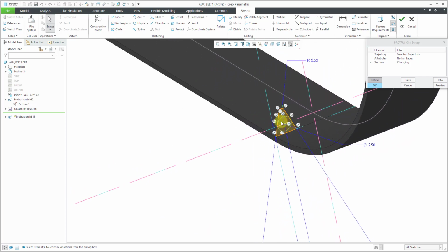I could have just taken the dimensions and figured out how to recreate it, but instead I hit the save button when I was in sketch mode in order to save this sketch out to disk, and then I found it where it was on my computer. I renamed it and dropped it into my palette folder, so I should be able to access it from this button. Let's cancel out of here,